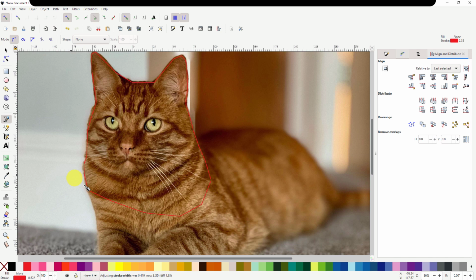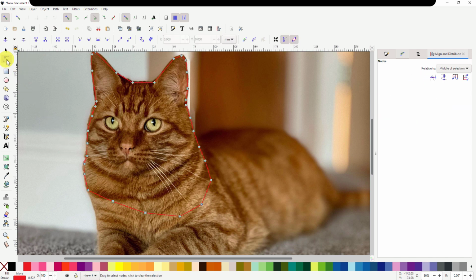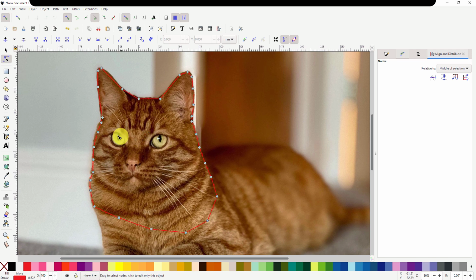If we want to make some adjustments to the line, we can just go to the node select tool. There are different options now. We can go and move nodes in the direction that we want the shape. We can go and drag the lines if we want to make adjustments, and we also have an option drawing a box on all the nodes, and we can try and make them auto smooth. That will make all the lines a nice smooth line.